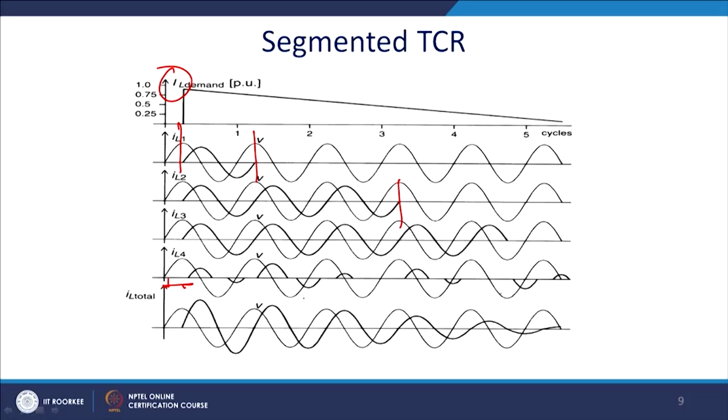So, gradually you can find that the current flowing through these devices gets reduced, and it is almost sinusoidal, because only this fourth element will have alpha control, the others will not. For this reason the current is gradually damped. So, it can be effectively damped in this way, and thus you can handle the power quality as well as the reactive power demand as required by the devices.